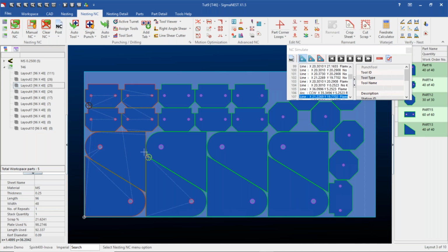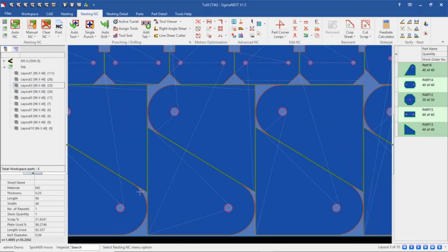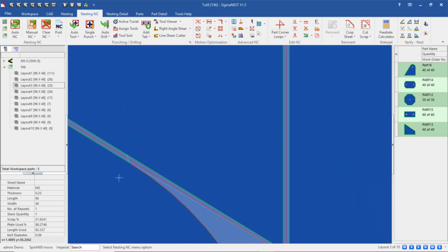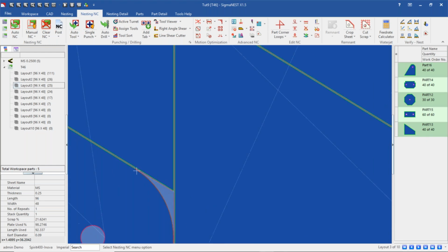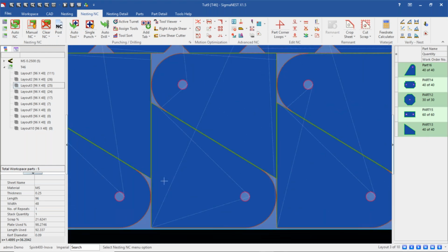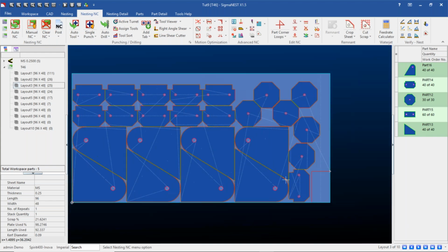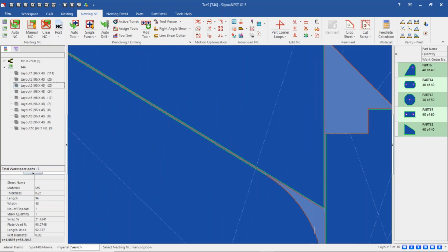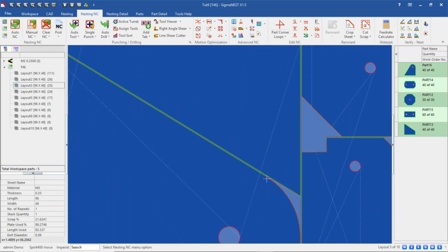Okay. Now we do have a radius that's also here in this part here. And if this is the case, if you wanted to use the transition option to actually put in a transition point, you can. Usually it's when you have two radiuses that are on both sides of the common cut. In this case, there's only one radius side, so this would be okay.